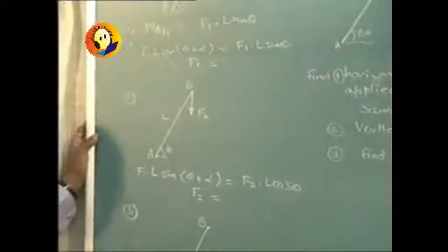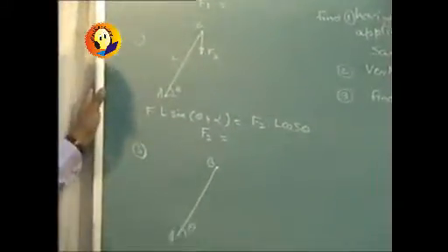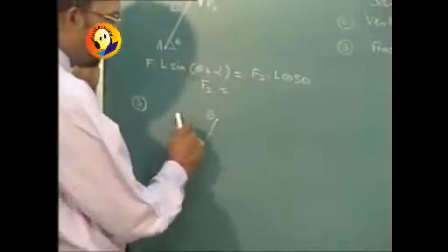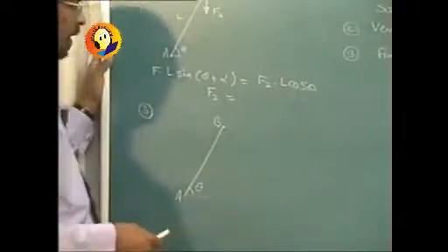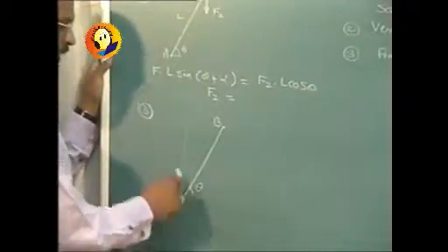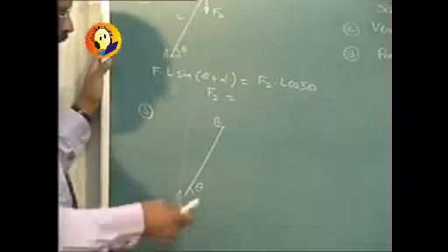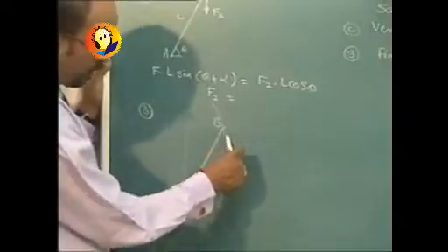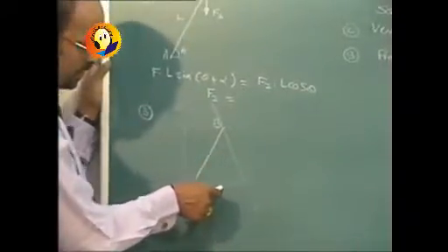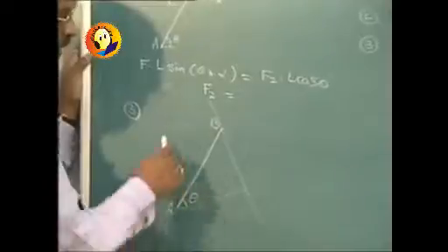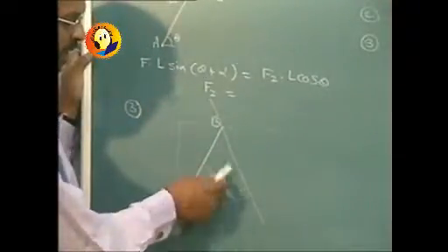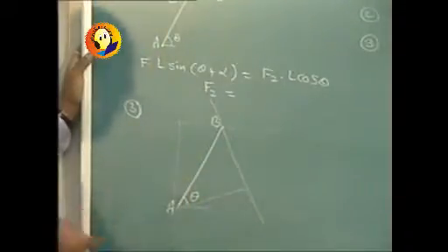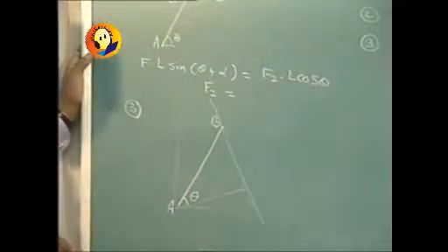In the third case, it is said that we are required to find the smallest force. Now the force can be applied, say, in this manner, horizontally, in one case, then the distance is going to be the vertical distance. Now if I apply a force in some direction, say like this, then the perpendicular distance will be this one. If I apply the force in any direction, every time I will get a distance which is going to be smaller than length AB, that is L.